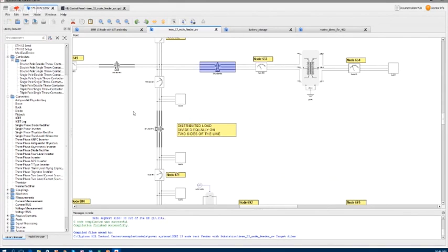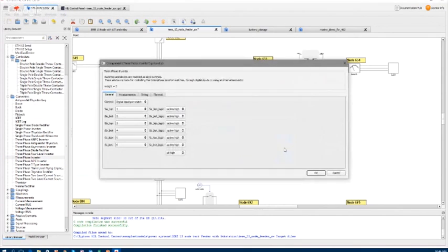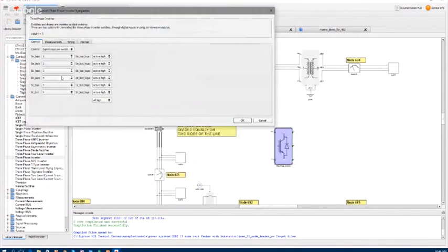So nothing complex. If you need some converter topology, this is how you model converters in Typhoon HIL. Just drag and drop them. That's it. If you want this converter to be controlled externally by a real controller, you just choose which control signal you want to use to drive which switch inside the converter.